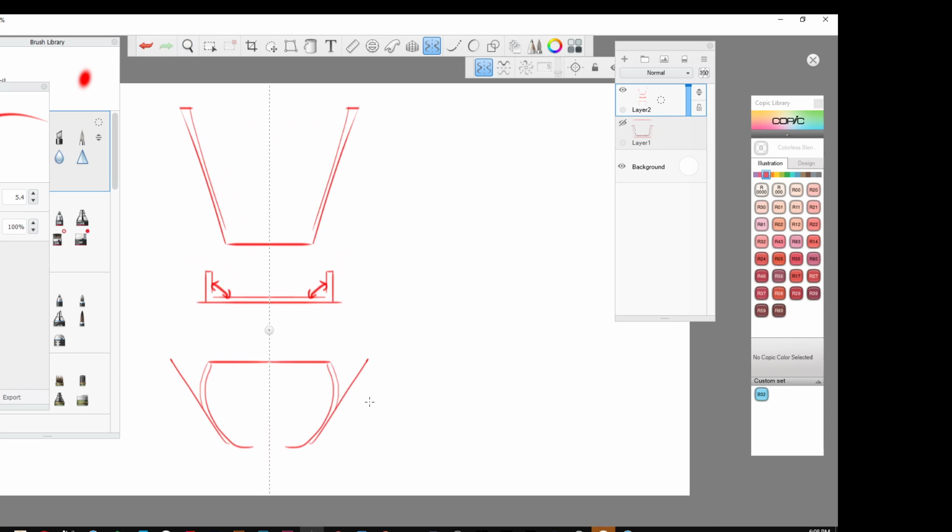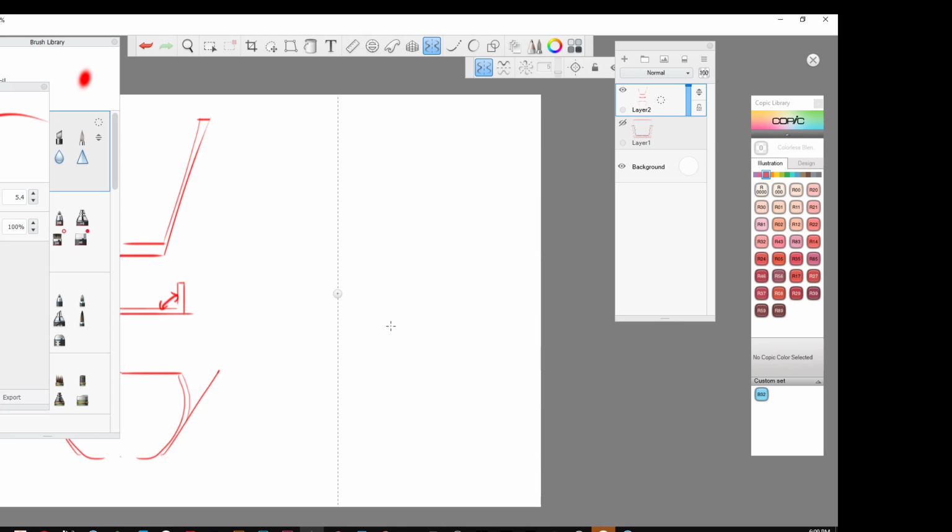Now, a few other things come into factor when I talk about material. And part of it too is it's not only to allow the tool to get off easier, but it's how the tool will interact with the part. So more often than not, what happens is tooling will scrape as it's coming out of the machine, or as the part's coming off, because you need to have it extremely tight. Now, what that scraping does is it causes marring. Now, it's not so bad if it's causing some marring on the inside of the part, but when you have a highly polished outside and you get scraping, that becomes an issue. Especially if you're doing clear acrylic pieces.